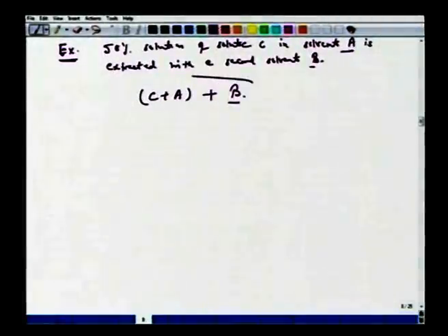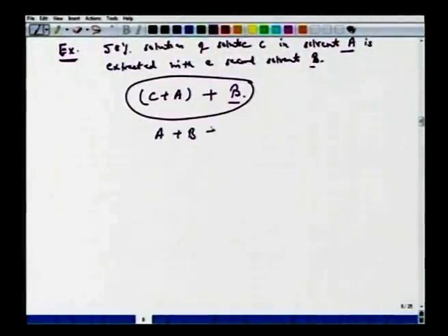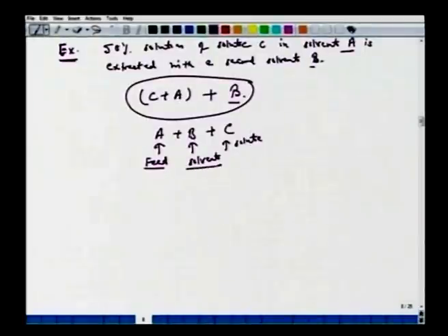So still it is a ternary system. We have A plus B plus C. C is the solute, A is our feed that becomes the raffinate phase, and this B is the solvent that gives us the extract. Alright, it's given that the weight of B is 25% that of the feed. So B by F, or A, is given here as 0.25.